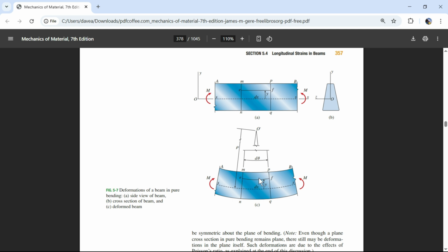This side is going to have those same 2 forces, equal and opposite in direction. If this moment goes this direction and that moment goes the other direction, this is what we call positive. We would say these moments are both positive, causing this thing to smiley face. So if you want something to bend in the shape of a smiley face, you have to apply this arrow in that direction and this arrow in that direction. You can do this to a ruler.